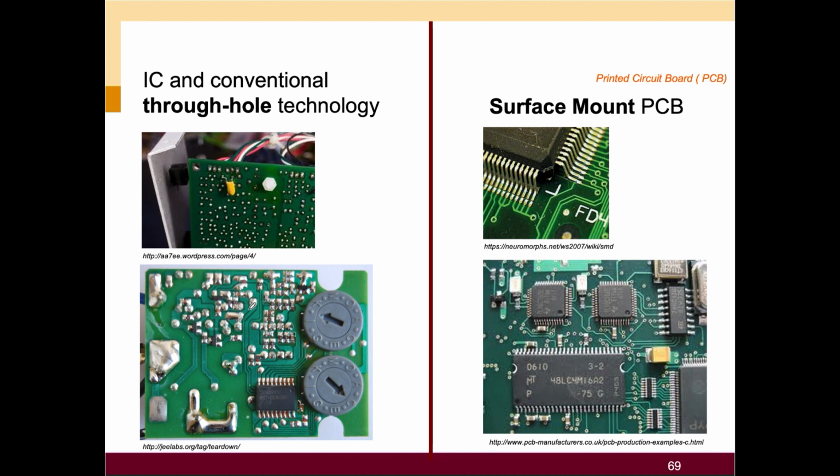If you put the notch the wrong way, your circuit will not function. Same goes to the surface mount PCB. Over here you need to program all, so you need to know how to identify the number of pins.